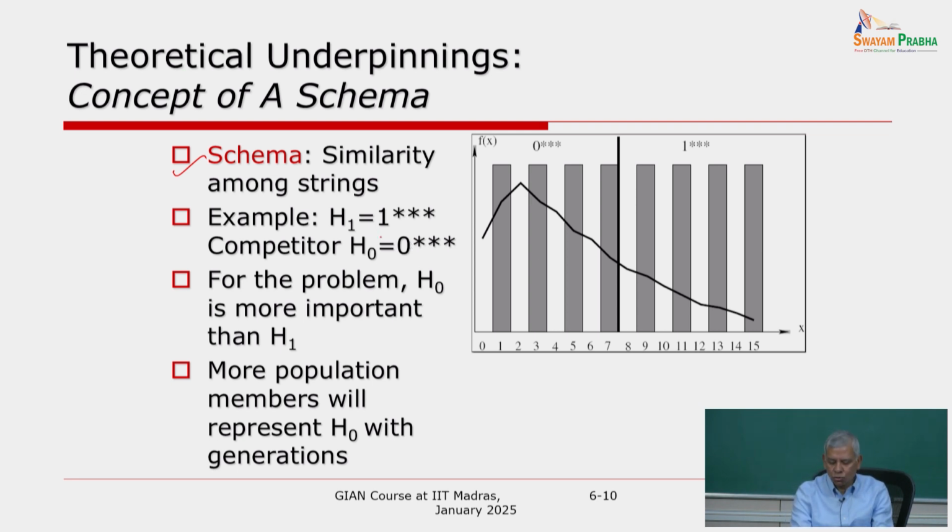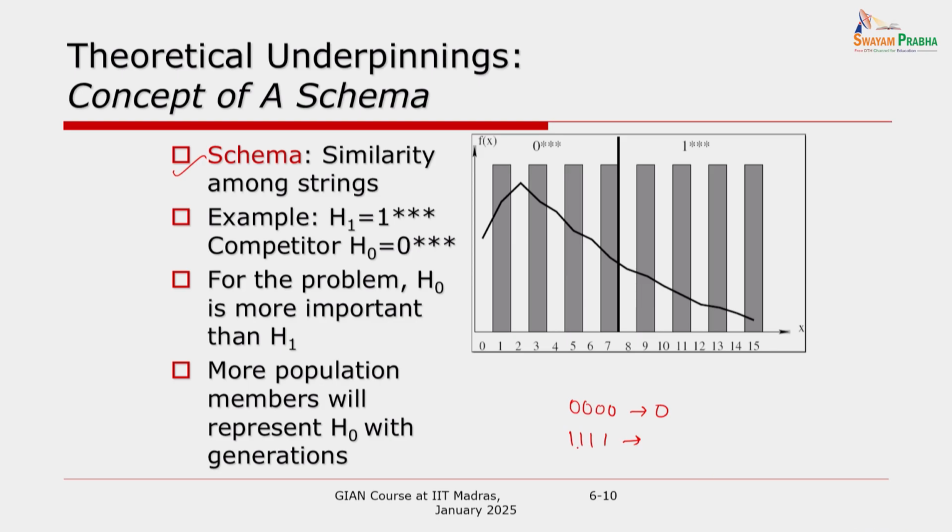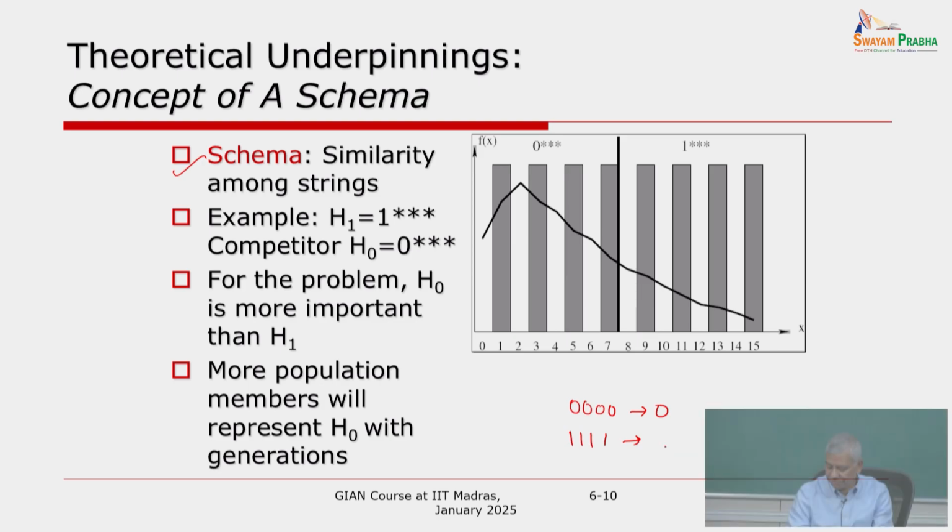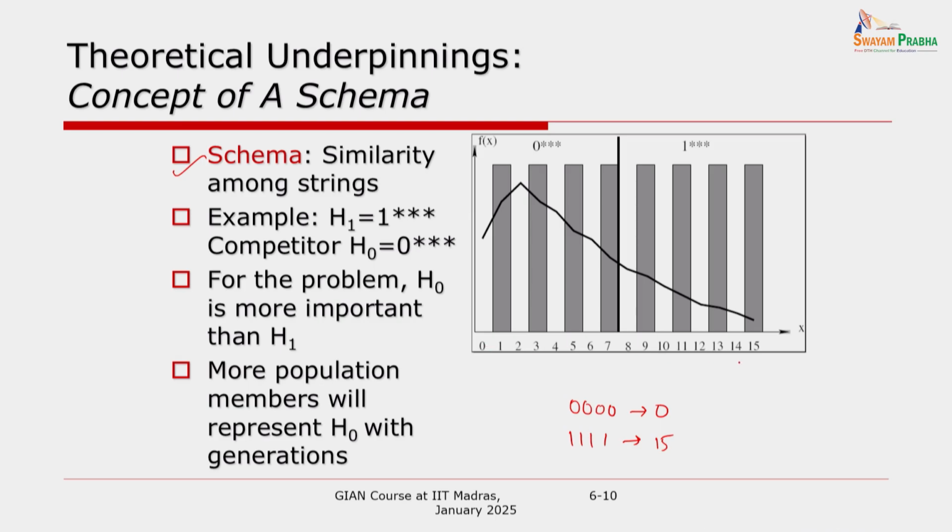So we have a total of 2 times 2 times 2 times 2, or 16 different strings. And here are 16 strings, 0 to 15. When you decode all zeros, you get 0. And when you decode all ones, you get 1 plus 2, 3, 3 plus 4, 7, 7 plus 8, 15, right? And any other string will be decoded to a value here, okay?